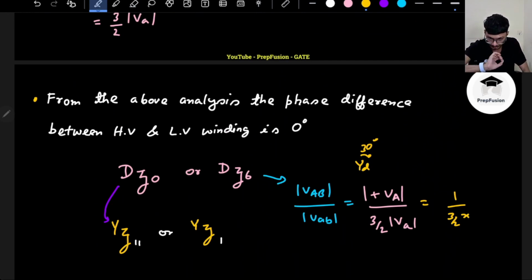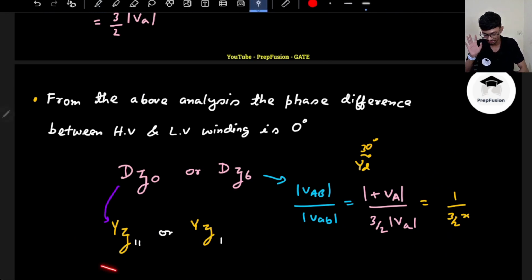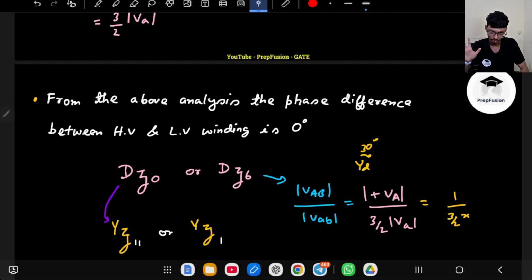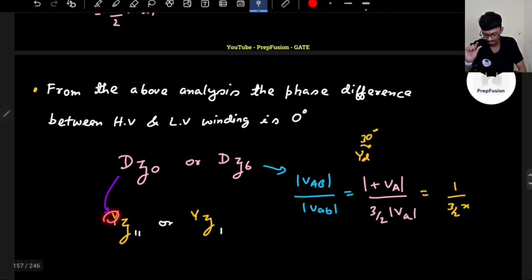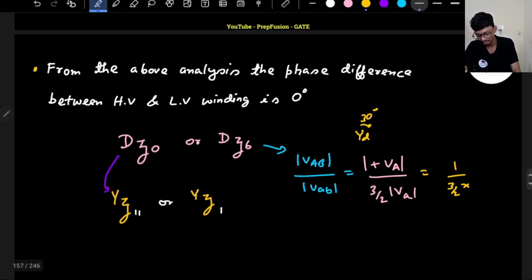So no need to remember this formula. Please draw the circuit diagram and derive, because for this the formula will change. What will happen now? The star and line, the phase and line voltages will be different, because it is star connected. So that's why I'm not telling you to remember the formula, I'm telling you the derivation.